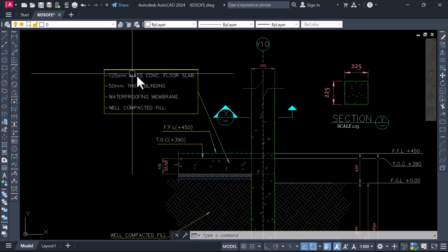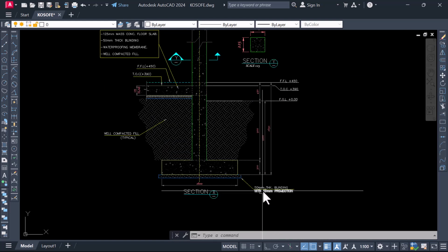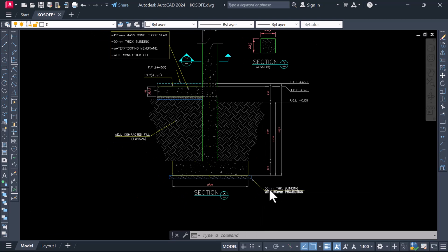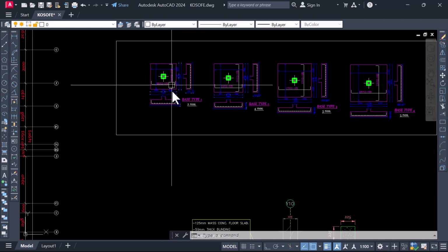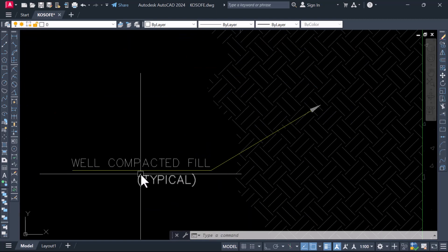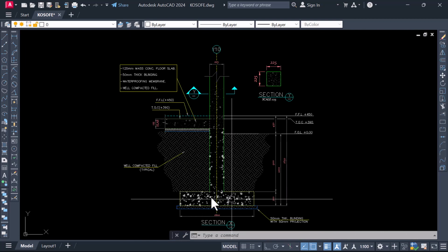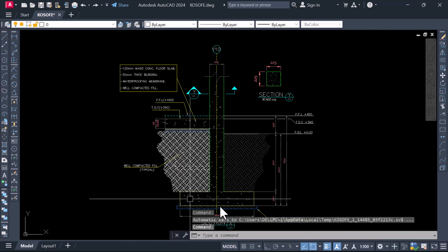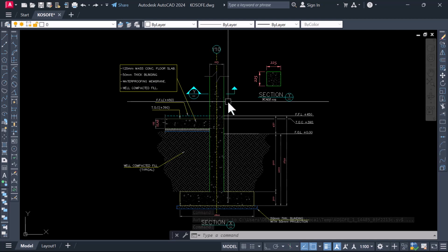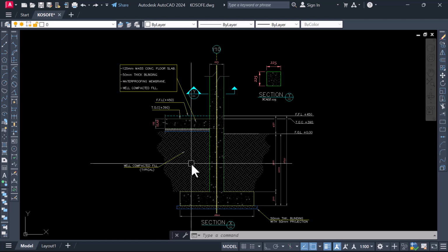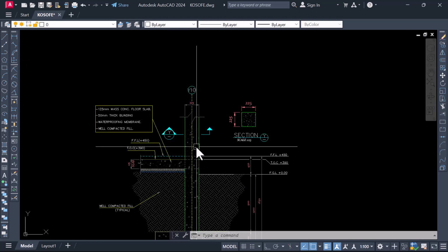And you can see the mass concrete that we've already cast. All right, this is what we've already cast along this area, and you can see my screening of 50. So I did 50 millimeter for the wall area, and I did 100 for the pad base. That's what I've done here, and you can see the compacted filling after you might have done your blinding and your concrete work, and you've already established the block work along this area that we need for backfilling, and here will be your section for it.